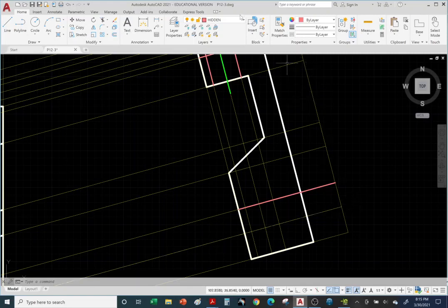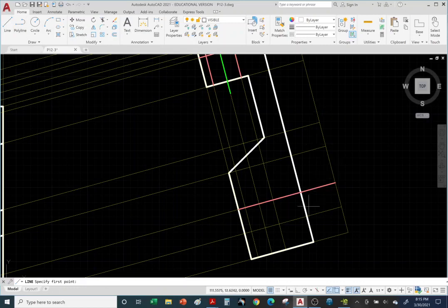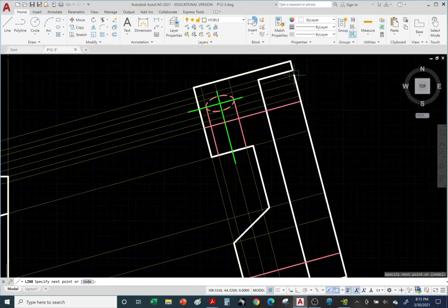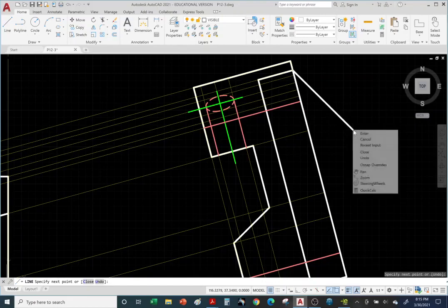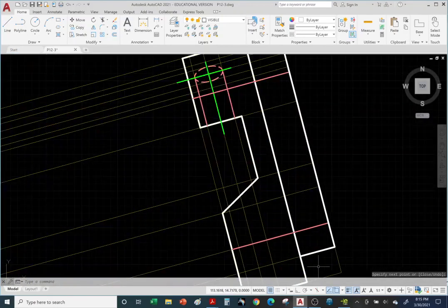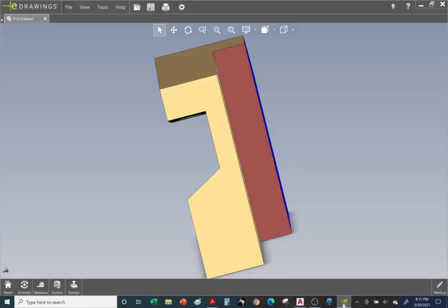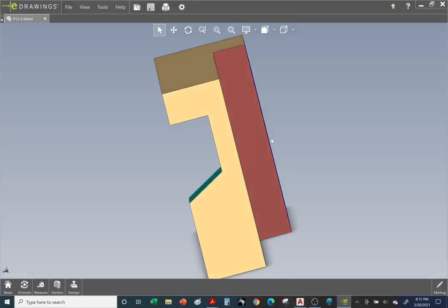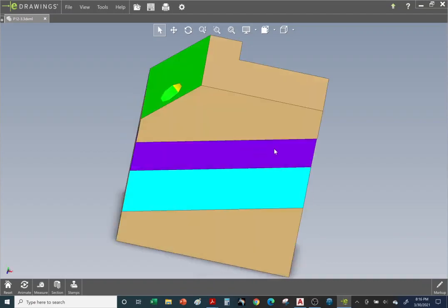we'll go up. Okay, so let's go to the visible object layer and line command. And notice I have ortho off. Okay, so I'm going to go from this corner to this intersection point and work my way up. And there it is, right click enter. Okay, so now it looks like our 3D model, our auxiliary view. There it is, right? Looks like we have everything except the dimensions. Okay, looks like we are good to continue.